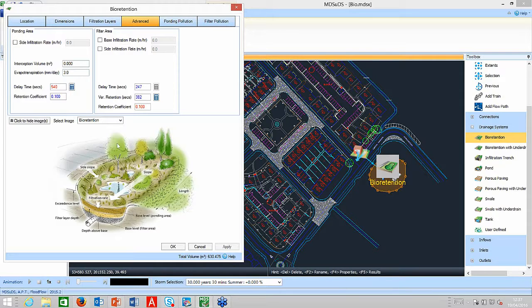That's the benefit, again, of having the green infrastructure within the basin itself. And here's a really interesting aspect. In future webinars, I'll look at other structures as well, such as swales. And within the guidance, we're being asked to retain the flow, delay the flow, hold it on the surface, slow down the flow. We're trying to reduce the peak runoff. We're trying to reduce the peak volume.